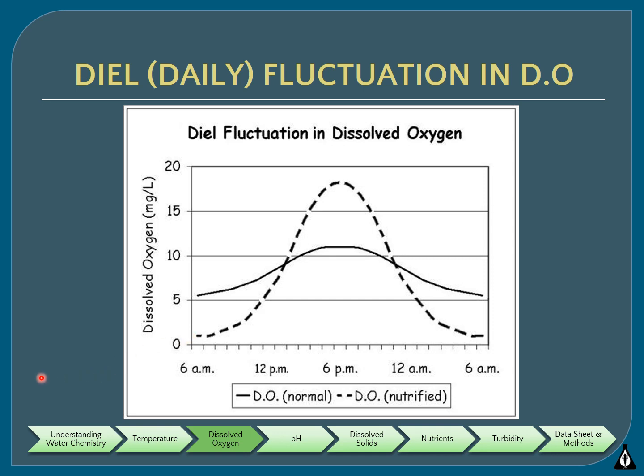Why is the dissolved oxygen lower at 6 a.m. here than at 6 p.m. here? Well, it's lower because algae and other aquatic plants switch from photosynthesis to respiration at night and are therefore using oxygen, not producing any oxygen at all over the night period. So the only source of the dissolved oxygen during this period is a result of physical aeration in the stream as water tumbles over rocks and other obstructions.